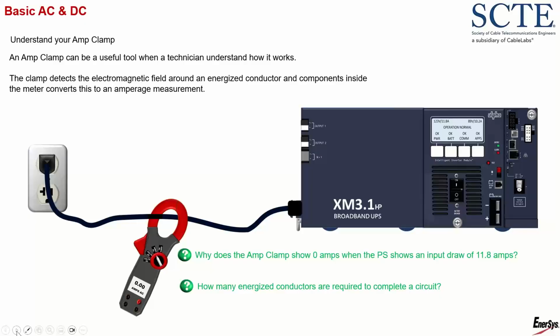Amp clamp. So like I said, amp clamp is one of the tools that I see a lot of technicians get that they don't understand. An amp clamp is an inductive device. Underneath the clamp part is steel.